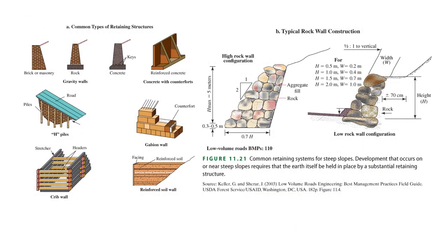Environmentally sensitive design is especially concerned with steep slopes, one of several sensitive landscape features that in principle should either not be developed or else aggressively protected from erosion and instability. Steep slopes may be geologically stabilized through a variety of retaining wall systems. Soil erosion can be prevented with fabric-based methods that use plastic netting, wood mesh, nylon mesh, or paper twine to hold soil, seeds, and new vegetation in place for planting and cover.